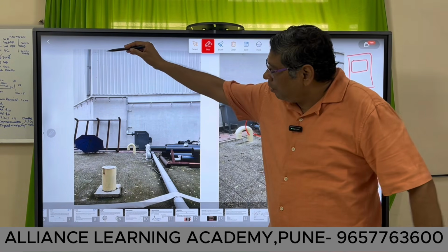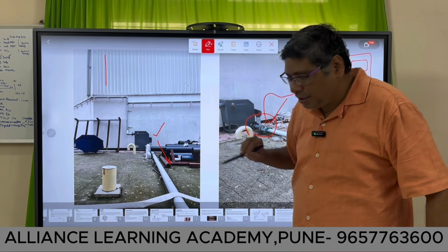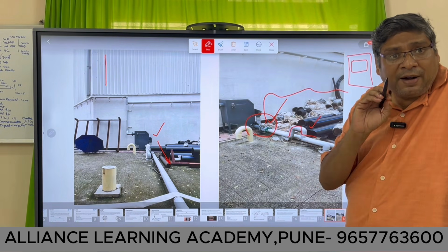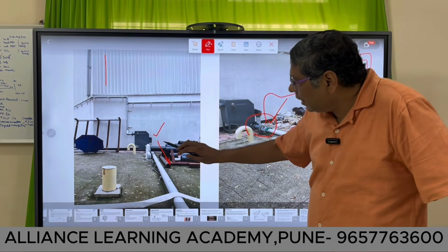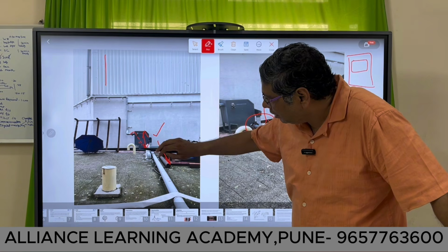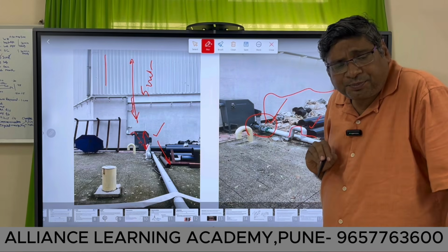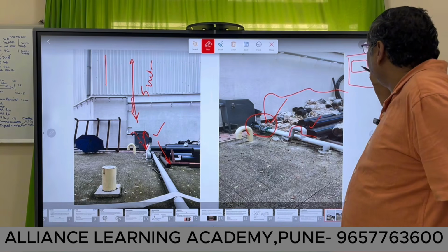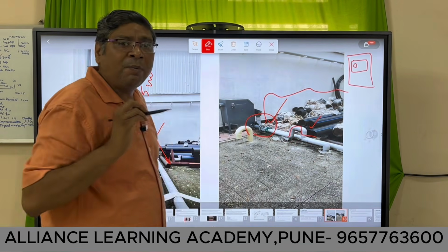Water is coming from up, it is filling this filter, and then water is coming from here to here. Now the problem is the dead zone or dead band, because you know an electromagnetic flow meter is a velocity meter. Here it is getting very little velocity due to this filter, and water is falling down here. Say okay, it may be 5 meters, no problem. But every time they run this system, the reading in this converter is always 0. It is not a problem of the flow meter.